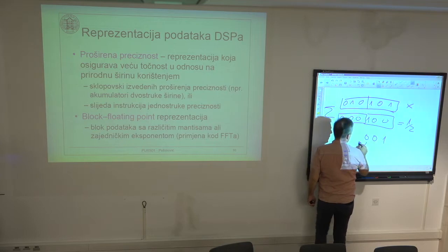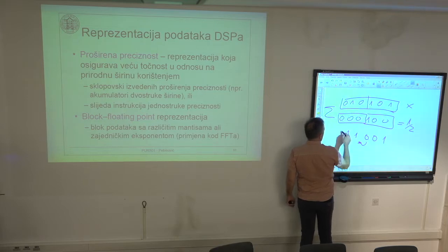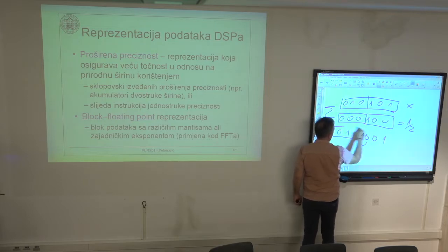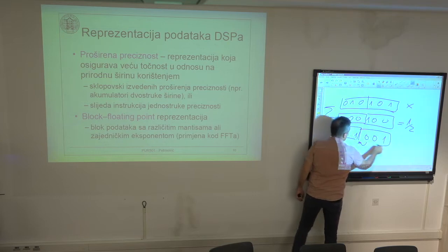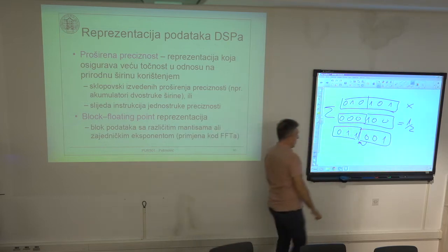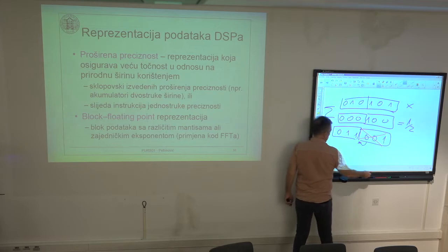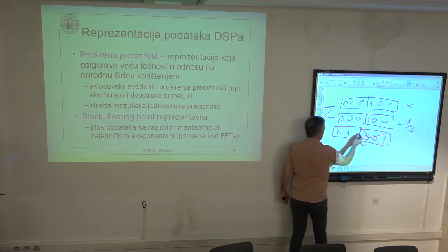This carry then causes 1 and 0 and 0 to be 1, and so on. Now I have this result, and then I truncate the lower word. So after adding 1/2, I truncate the lower word, and I get the rounded value.